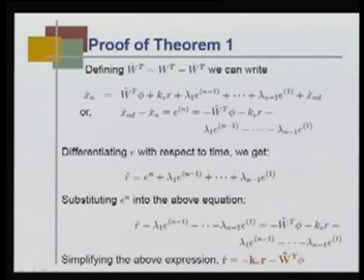So, whatever we did earlier, just to summarize, we define this. x n dot becomes W tilde transpose phi plus k v r into this. You bring x n dot to this side, or you can take it to the other side also, and then you can write that the nth derivative of the error is minus W tilde transpose phi, and this k v r will go to the other side as minus k v r, along with all these terms. Differentiating R with respect to time, you get R dot is this quantity.